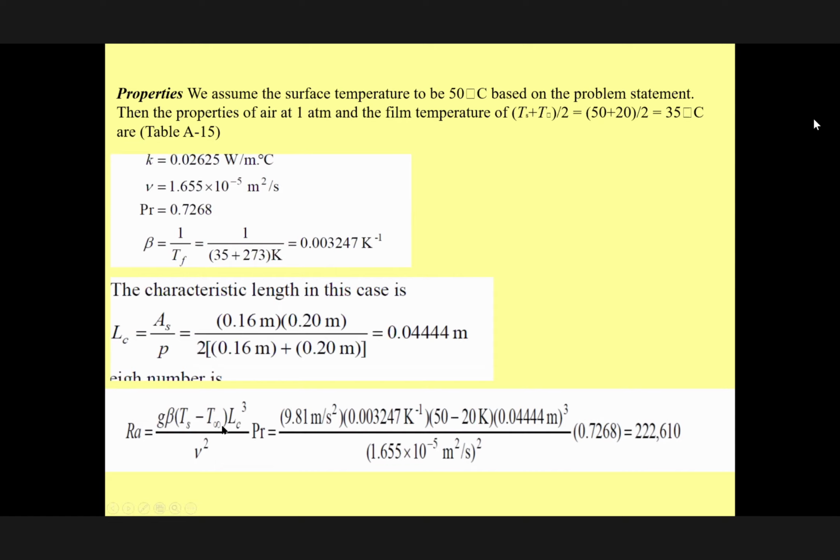This is the most common problem students make in the exam, okay? Therefore, we're going to put this equation. Again, this is the Grashof number times the Prandtl number, which becomes the Rayleigh number, this value here. Now you go back, and it doesn't matter if it's top or bottom, okay? Because the Rayleigh number will only depend on this characteristic, not the temperature difference. Therefore, based on this number, you can calculate the Nusselt number for the upper plate and the lower plate, okay?